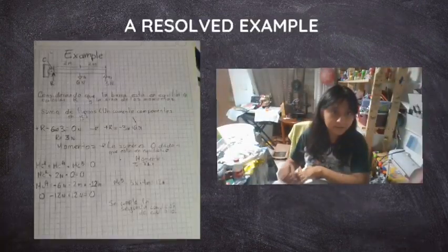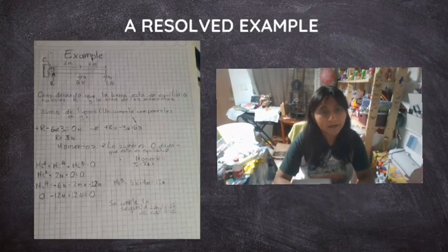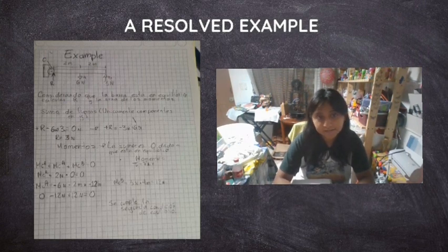verify the solution. Now, in this example, I put as object a metal lever that rotates on an axis C, and the weight of the bar is the 6 newtons that are in the middle of the lever, while the 3 newtons are an external force. The first thing I did was calculate the force at R, given that it's mentioned that the lever is in equilibrium.